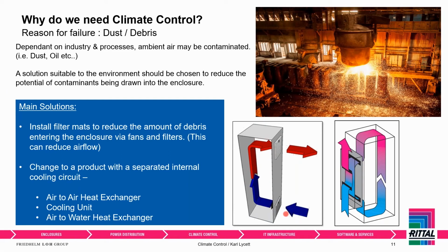But yeah, so the cold air is coming in the bottom, and then the hot air is retreating out the top, and this just continues, and debris is going to constantly come in and out of your enclosure. However, if it is a very aggressive or dirty environment, air cooling, fans and filters are a no-go. You don't want to be doing it. If your place looks like the picture in the top right-hand corner, don't even think about it. You want to be working with a different type of product which has a separate internal cooling circuit.